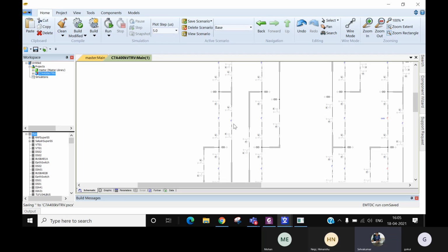Yes. And when the breaker restrikes, what will happen? There is already a voltage in the reactor, and when it restrikes, an additional voltage is pumped into the reactor. Assume 1 per unit voltage is already there in the reactor, and now you are adding one more strike. This adds maybe if not 1 per unit, at least some more per unit to the existing voltage. Again the breaker will attempt to open, and if it is 2 or 3 restrikes, then the voltage on the reactor or load side is extremely high, and your breaker will not be able to interrupt that fault current at all. Yes, you got the point, the breaker completely fails.